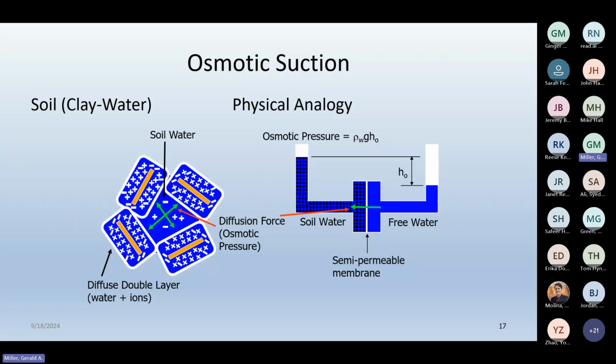All right, so just to give you some sense of what osmotic suction may look like, it's not that salt doesn't affect soil behavior, it does, especially clay soils, not so much in sandy soils. In clay soils, the salt is going to affect the diffuse double layer, those films of water and ions that surround our clay particles.